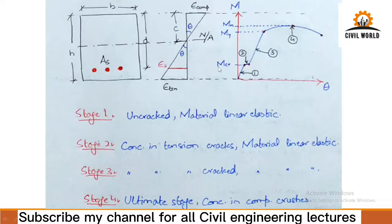So you have cracks initiated in that section. There is an increase in curvature but no increase in load for a small instant, and then loads are transferred to the steel. So all the tensile stresses are taken by the steel. It again starts to increase linearly.